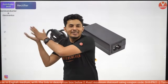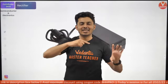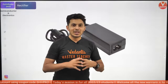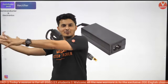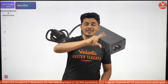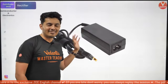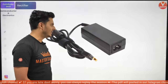Hence, you need to convert that AC into DC. Once you convert AC into DC, the current only flows in one direction, and then it can charge the battery only in that particular direction. Is that making sense? That's why whenever you have to charge a battery, you always use DC. Your mains socket, that power socket, is always AC. You convert that AC into DC. That's very important, and that job is called rectification. All your electric vehicles will always need this rectifier, because when you connect your power supply, they have to convert that AC into DC.